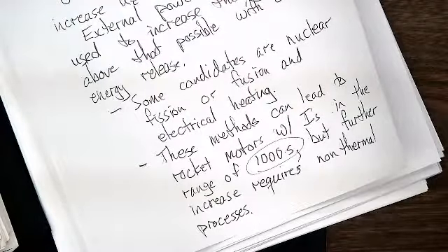So what's the limiting factor? You can always add more heat to a gas. Our problem becomes materials. You have to have a nozzle with an expansion in the nozzle throat, and refractory metals start to become soft right about 2,900 to 3,000 Kelvin.